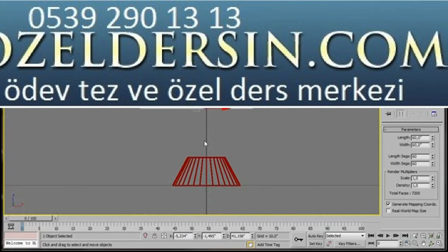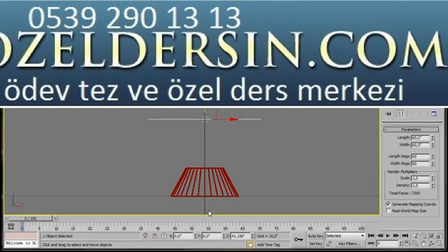Drop down to the Transform dialog at the bottom of the screen and bring the X and Y axis back to 0. Don't worry about the Z, that's the height. To create folds and creases, we need to drop the object from an angle. So first of all, let's go to the main toolbar at the top and click on Angle Snap Toggle. Then the Rotate tool. And now we're going to rotate the plane 50 degrees.